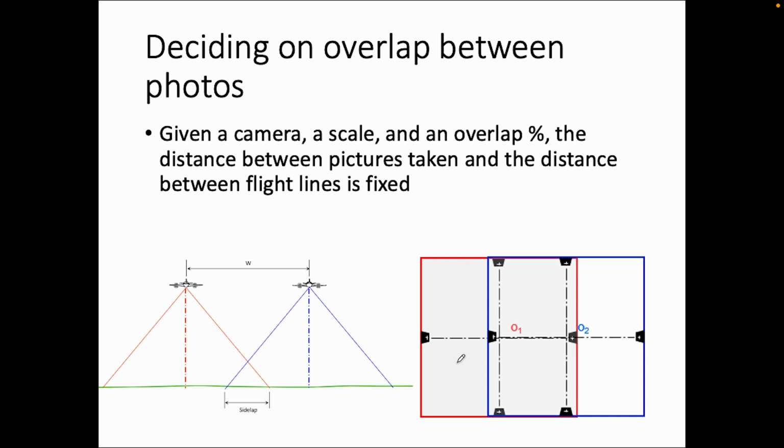That's from Pix4D. There are some other folks that have other recommendations. Aerotas recommends 75% and 75% for both front and side overlap, with values a bit higher for dense forest or tall buildings and agricultural fields. So same as Pix4D, use a bit more overlap for either very featureless areas or for forests and buildings, things that need a lot of 3D information.